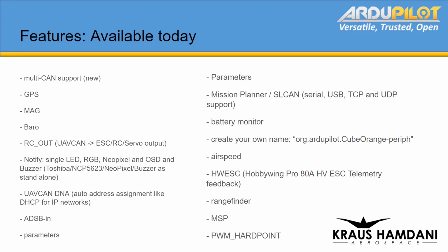You can make a node be a GPS. So if you have a u-blox or whatever kind of receiver, it can plug into your node, and then primarily the nodes talk UAVCAN back to your vehicle, and so it just emulates as a UAVCAN GPS or a UAVCAN magnetometer or a barometer or a whole list of different things here.